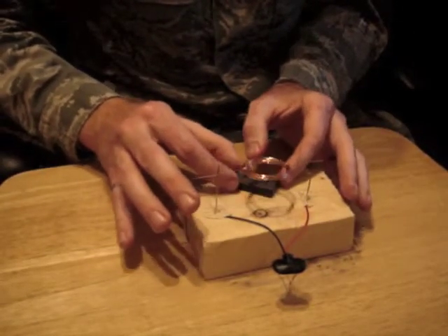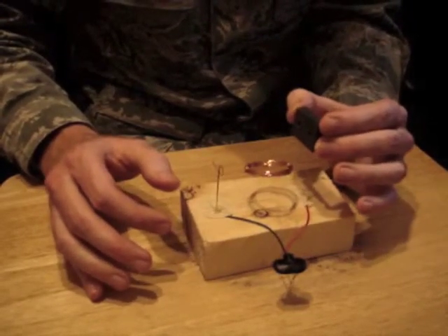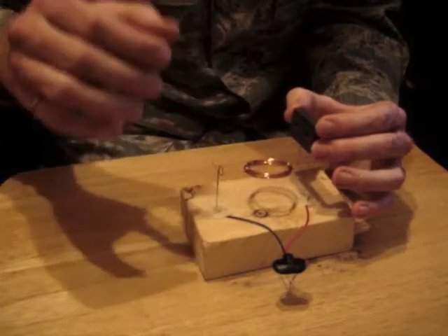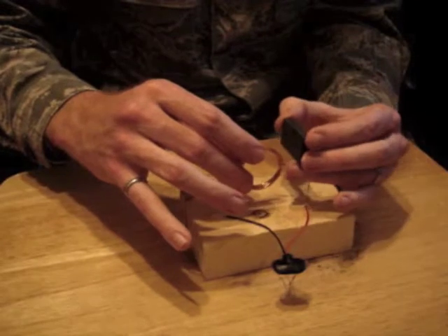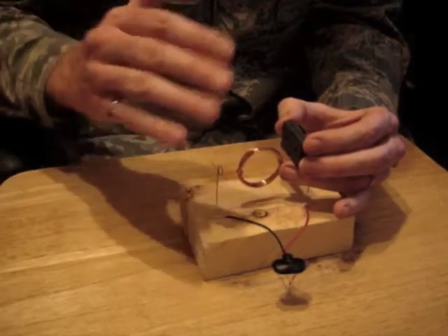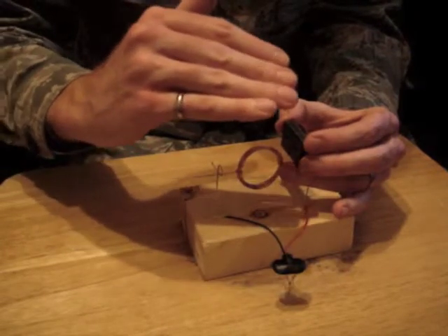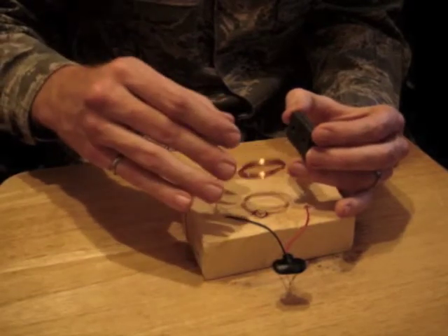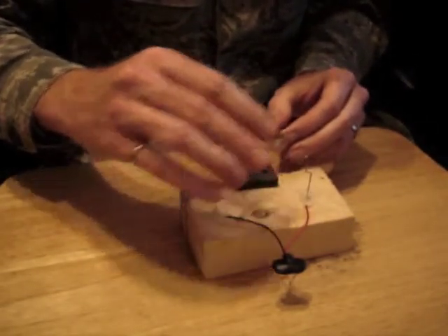In the second configuration, I'm going to move the magnet over to the right side, where the magnetic field lines are now protruding left. Using the right-hand rule, the current will be flowing this way when there's connection through the wire, but it is parallel with the magnetic lines, and thus no resultant force will happen, and no rotation of the rotor.